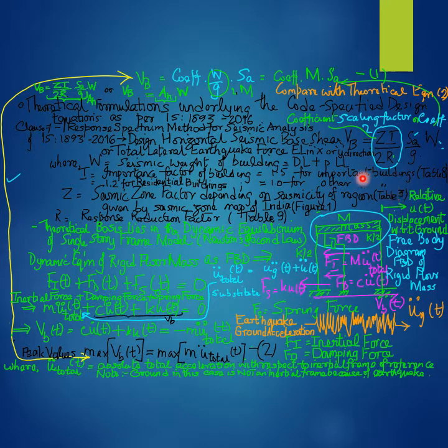Therefore, designating the single and the only degree of freedom, that is the lateral or the horizontal displacement along the x direction of the floor mass M, denoted as u, where u is a function of time or is a time variant function in the general case of the dynamics, or the general case wherein the dynamic response of the single story frame model is of interest.